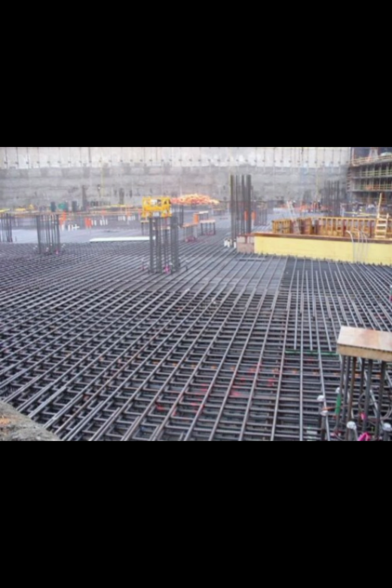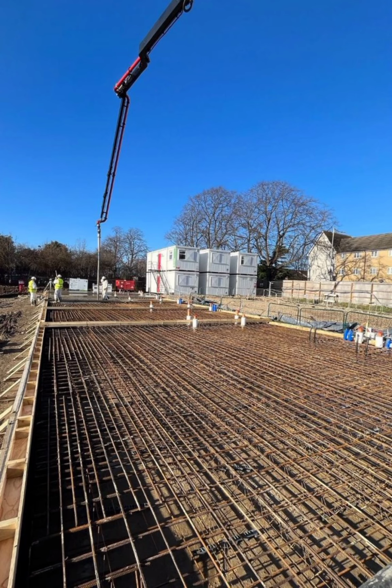So how is this constructed? First of all, there has to be an excavation of the entire area with a required depth. Then you lay your waterproof membrane if it's necessary. Then your concrete of desired mix ratio is poured over the entire area. Don't forget to provide your reinforcement as instructed by the structural engineer.